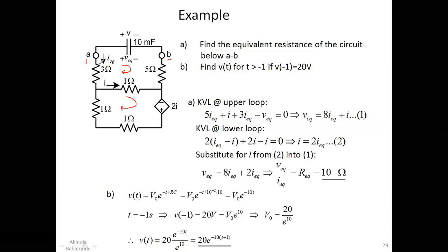What you will find out is that here, if we are starting from here, if we are starting from -5, what we are going to have from 5 ohms, because this is positive terminal and this is negative terminal. This is positive because you can see the current coming down through this way. Okay, so what you can have here is you have -5 equivalent, right? And then, since this loop current is also in opposite direction to the I on this 1 ohms, this becomes -I,